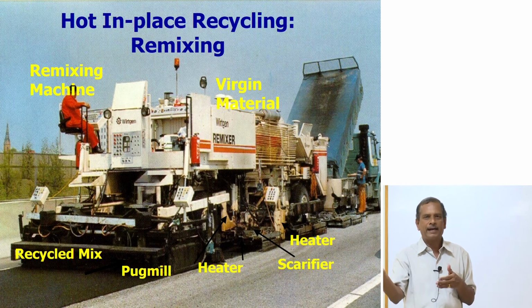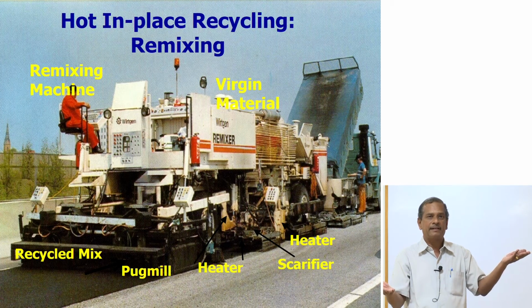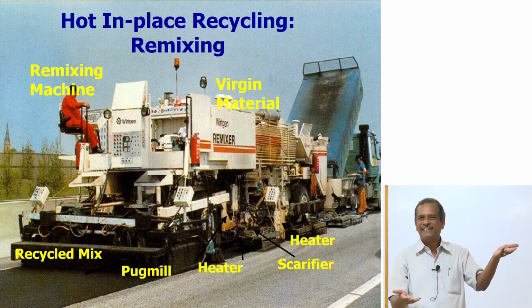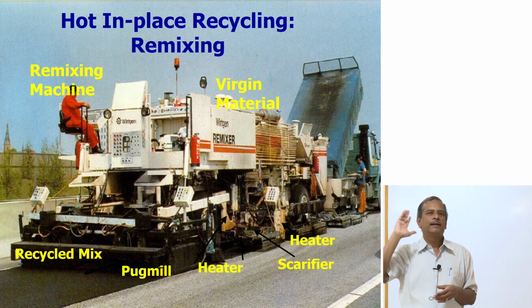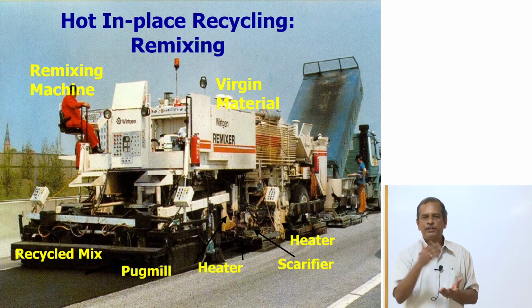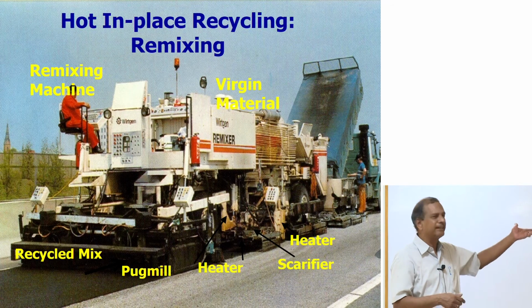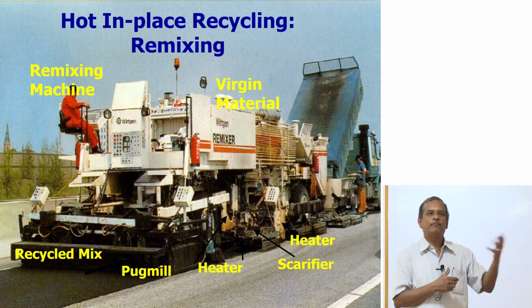So, construction is one hand, the maintenance is on the other hand. Maintenance challenges are like a doctor diagnosing a disease. You have a road that is deteriorated, for example, campus roads. The campus roads are deteriorated. These roads were constructed in the year 2009. Now, they are 10 years old. Now, what should I do? So, as a civil engineer, you should be able to tell, should I recycle? Should I use a modified binder? Should I adopt a white topping?